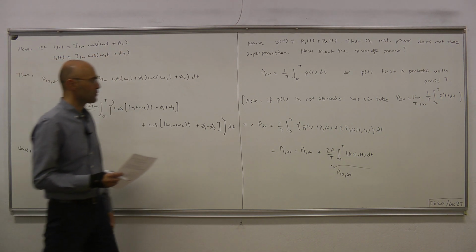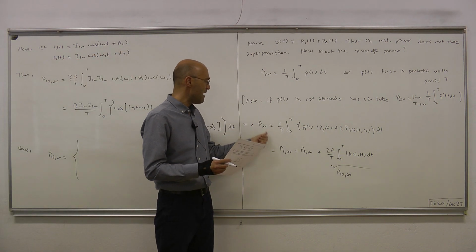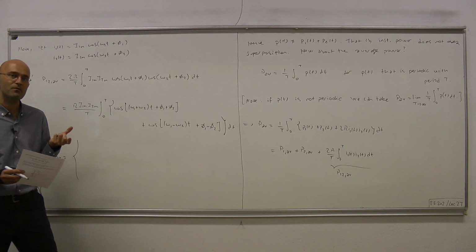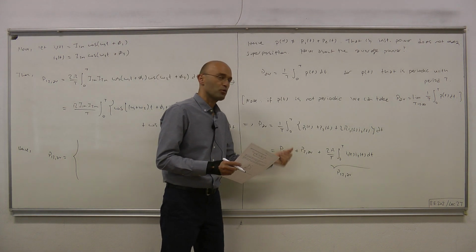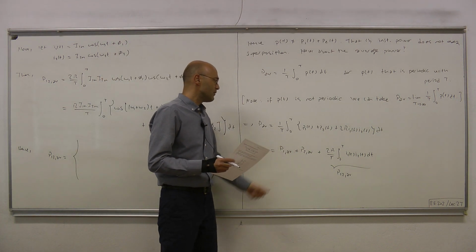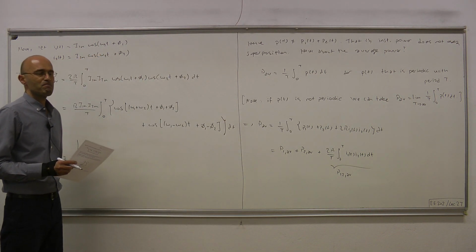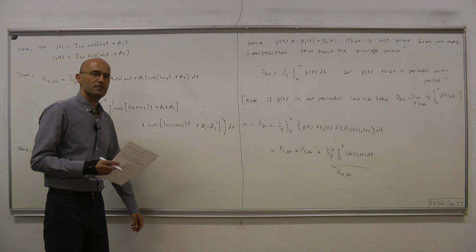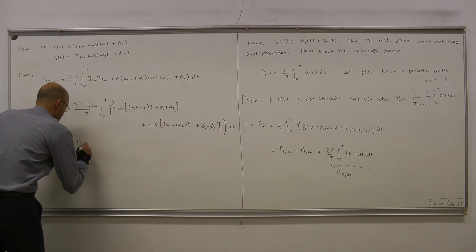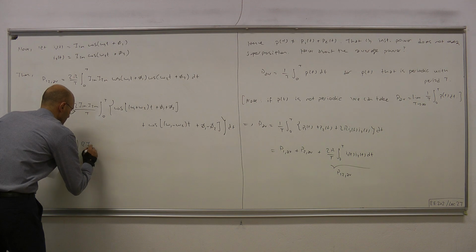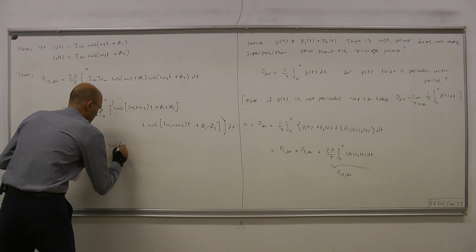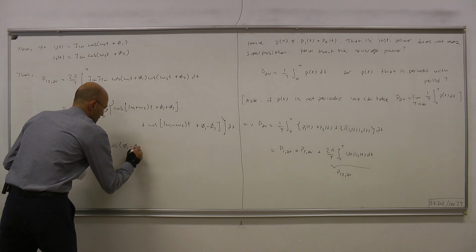Okay, and then what we'll be left with is P average equals P1 average plus P2 average, meaning that if the frequencies are different, we can apply superposition not to the instantaneous power but to the average powers, in a circuit that's in sinusoidal steady state. So P12 average equals R I1M I2M cosine phi 1 minus phi 2.